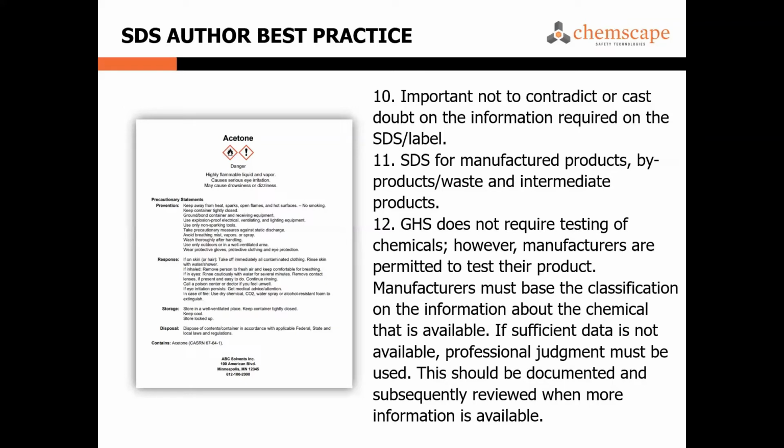There's also, I encourage you to do SDSs for byproducts and wastes. Now, depending on your jurisdiction, you may have other ways of dealing with waste, but an SDS helps. The SDS for your manufactured products, because we've come into that too, isn't necessarily the same as your waste. So you can't, depending on your waste, say you've got a flammable liquid, and now you've got a flammable solid in the end because it's been mixed with your sand treatment facility. Now this is a solid, so that SDS for your liquid doesn't necessarily apply to your solid.